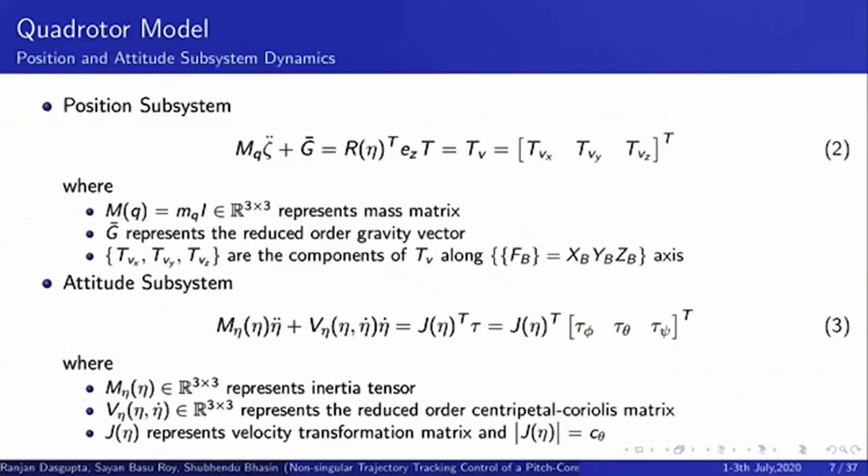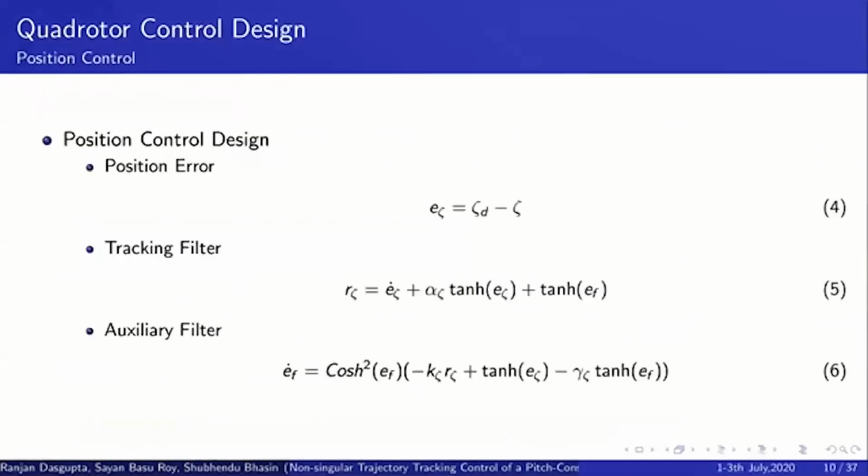We can observe that the entire quadrotorcraft system can be decomposed into 2 subsystems, 1 position subsystem and 2 attitude subsystem. It indicates that we need to design a position and an attitude controller simultaneously, separated by time scale. Current slide starts with the description of a position controller. The choice of filter variables in equation 5 and equation 6 are instrumental to provide singularity-free reference attitude calculation.